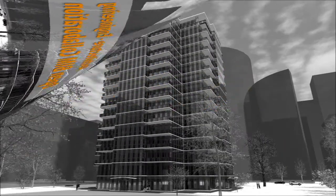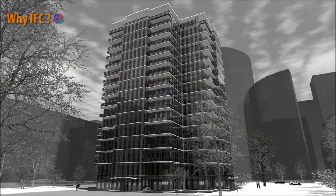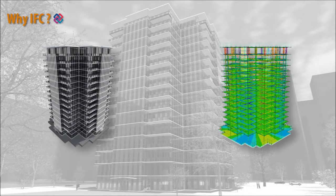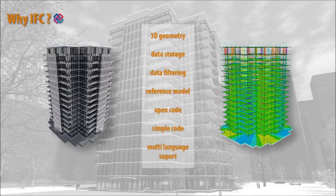ArchiCAD and AxisVM. Let's summarize the main features of the IFC data exchange file format, which is the basis of our Open BIM workflow solution. IFC describes the precise geometry of a 3D building element. For example, in case of a column, its height, width, and cross-section. In addition to geometry, additional building element properties can be stored. For example, its material or fire rating, acoustic rating, and the function of the element.